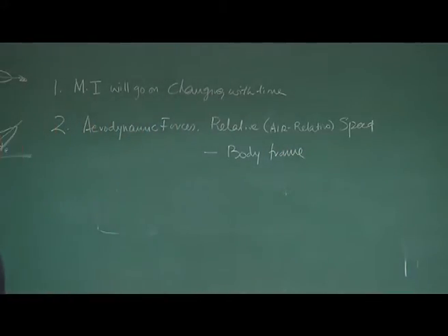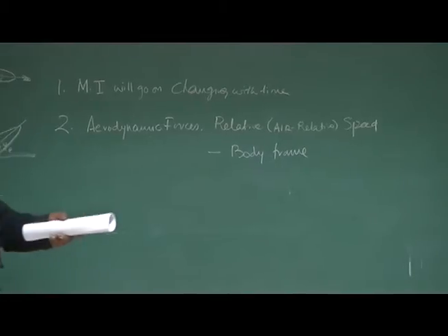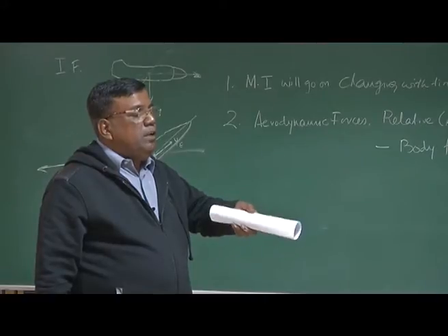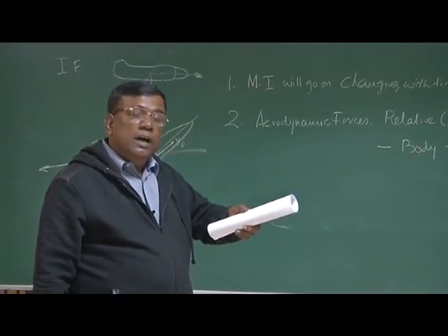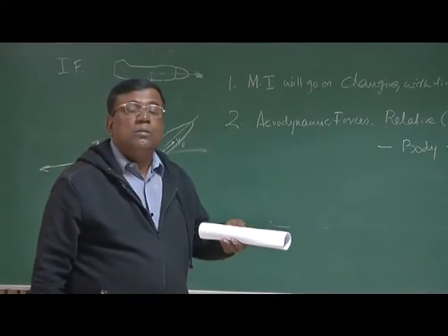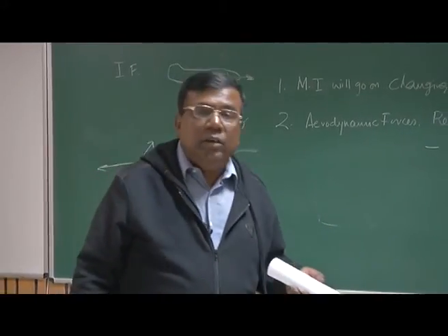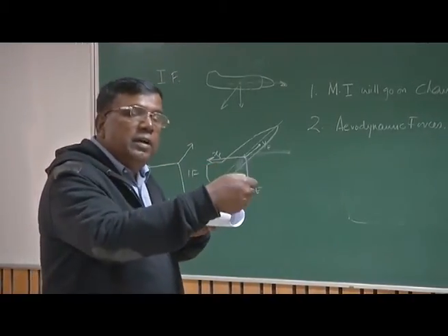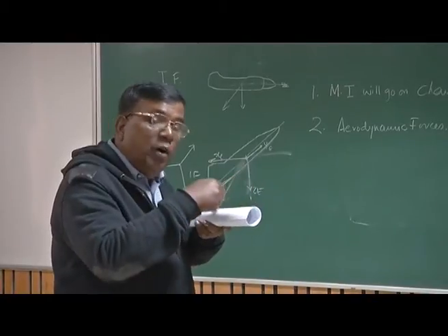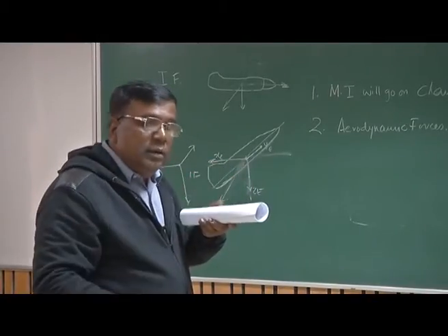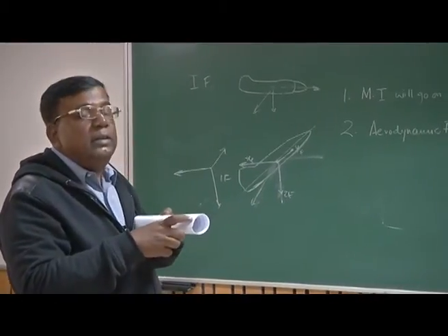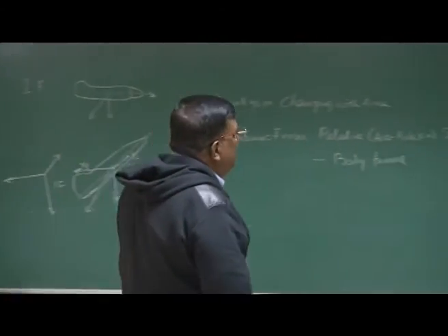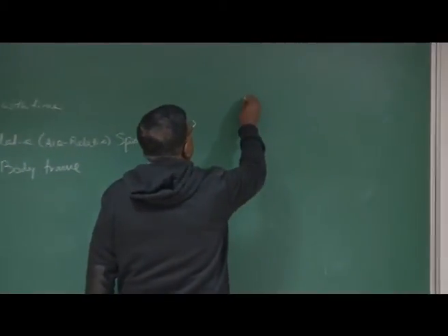Clear? So two things I repeat. As the body rotates in free space, the moment of inertia of the body about the earth fixed axis system changes. So we say moment of inertia will go on changing with time, that brings complication. And second point, because the aerodynamic forces depend upon relative airspeed with respect to the body, not with respect to the ground, I will be more comfortable to work with a body frame, and that is why we prefer working in body frame.